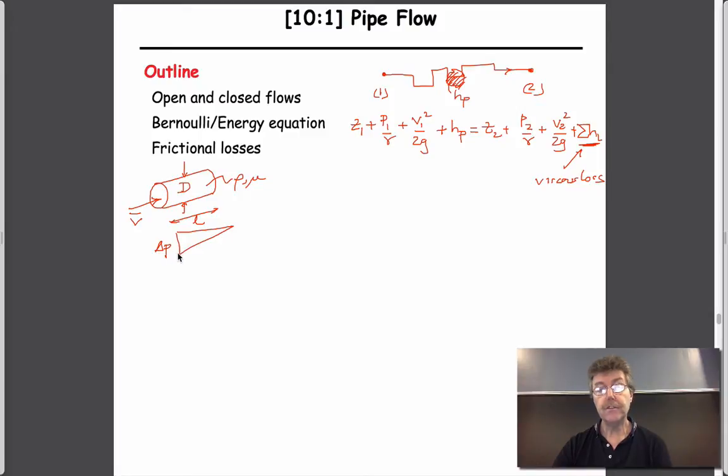We are going to try and get a kinematic similitude, which is probably going to be Reynolds number. And so we'll have d over L, presumably an important parameter for us. Reynolds number may well be important too: a velocity, a density, a characteristic dimension, any dimension, it could be L also, and a viscosity, a ratio of inertial and viscous forces, and maybe something that looks a bit like an Euler number. And so we can see exactly how that would work out.